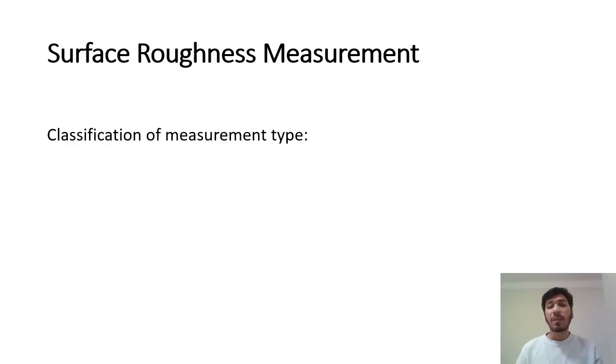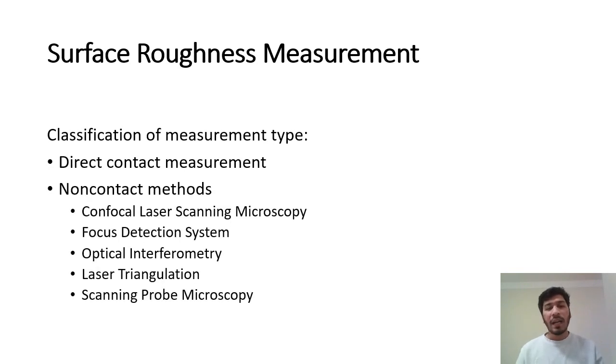One of the basic methods and the easiest to use is a direct contact based surface roughness tester. In these kinds of surface roughness testers, you have a vertical stylus that moves along the surface, and we are able to calculate the value of the surface roughness. These are handheld devices and user friendly, and we also use the same type of surface roughness tester in our AML lab.